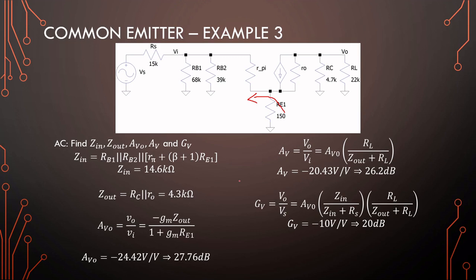In the case of a common emitter amplifier, it is technically a transconductance amplifier, and we use the collector resistor to convert it to a voltage. So this emitter resistor is increasing the output impedance of the current source part and not so much helping out with the voltage amplification part of impedance there. Anyways, so this is feedback, and feedback technically reduces the gain, so you get the opportunity to choose the gain that you want.